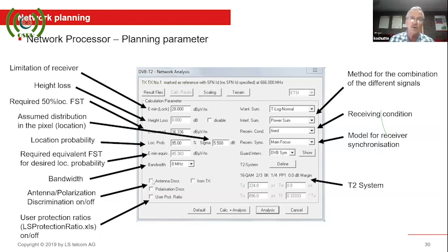It will look at what the attenuation is on the antenna in the direction it's installed, and it will subtract that from the actual received signal, because you will be losing some signal because you're not aligned with the actual transmit antenna.